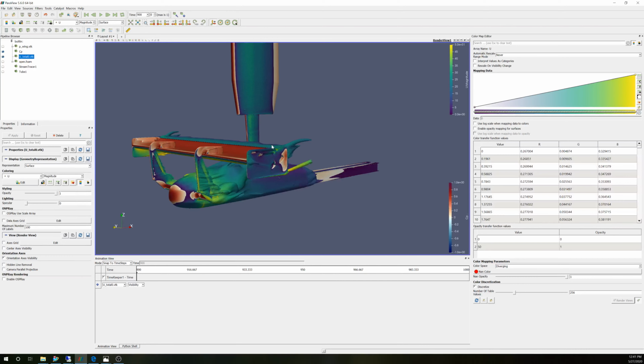So that's the reason we have those, and you can see what they're doing in this image very well, of the vortex at the top side. You can also see the vortex on the bottom side of the end plate that's also coming out. And if you're wondering what the slots towards the bottom of the wing are, that's also to help decrease the vortex on the top side. And that does not come with a loss of any sort of downforce number. So just so you know what that is. That's kind of what we're looking at in this image.